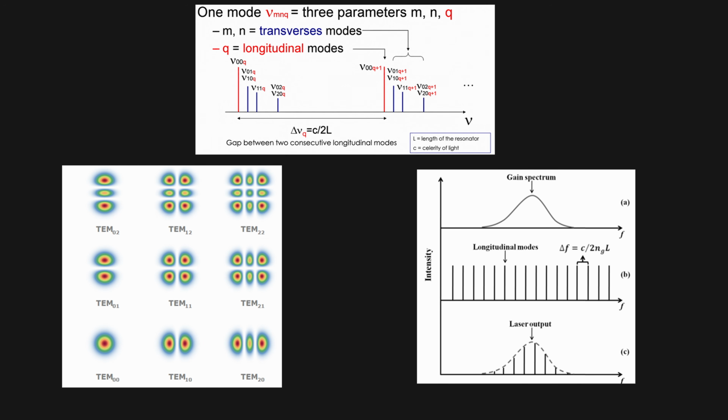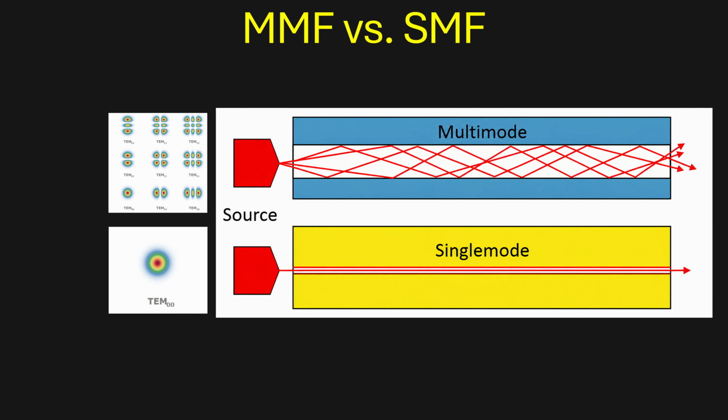The optical field has a transverse mode and also a longitudinal mode, which corresponds to a wavelength and frequency. A single mode fiber is small enough that only the fundamental mode of light will be guided and propagate, while the higher order modes will escape into the surrounding cladding and dissipate.